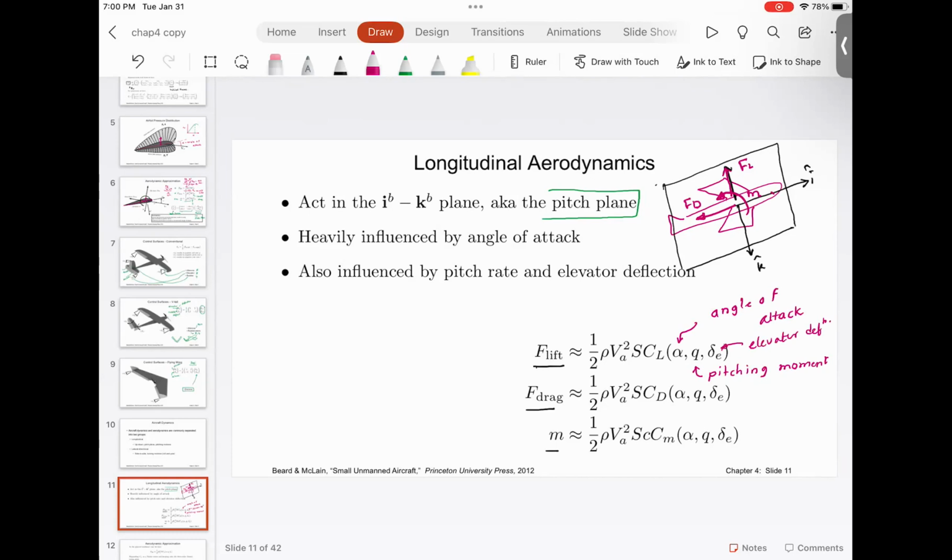And I just want to tell you, don't get intimidated by all these terms. The way we do it is, once we derive these big expressions, there is a design data book for each aircraft. For each aircraft, all these coefficients are given to us. So when we are programming, it's actually very simple. There is a standard file format wherein all this aircraft data is available. You write the code in MATLAB or in Python, you actually go read that file and basically populate all these aerodynamic coefficients for that particular aircraft.